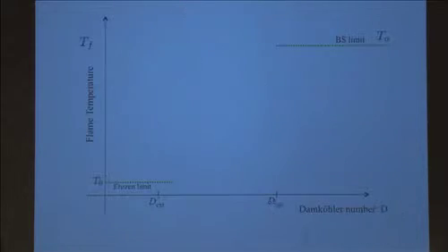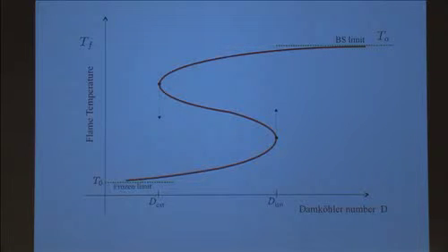So essentially what we have described is, again, this S-curve. We were able to describe this whole turning part of the S-curve, including the extinction point and the extinction condition. So there is more leakage and the flame temperature drops from the adiabatic value.